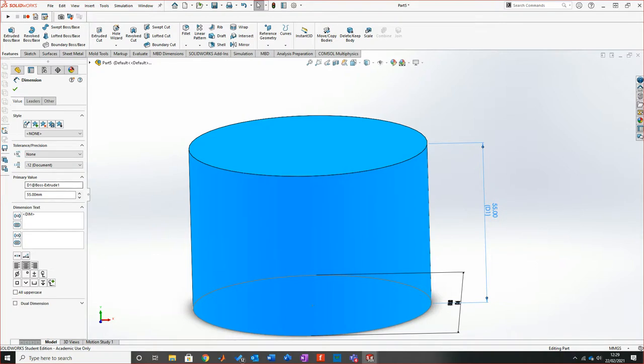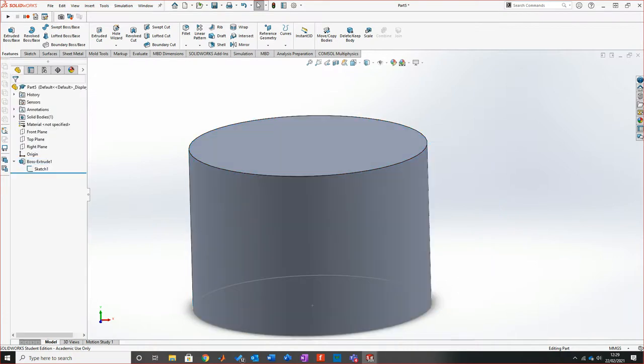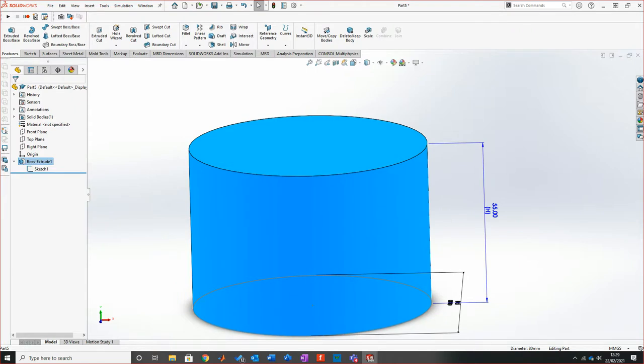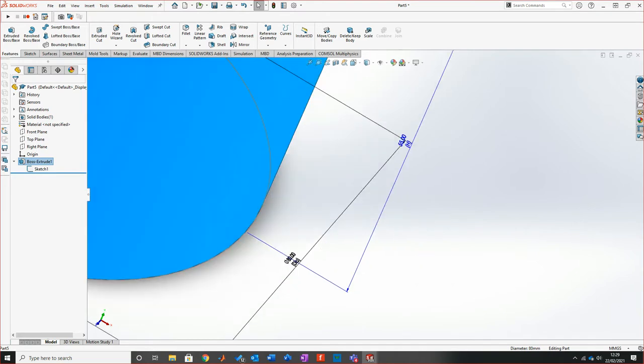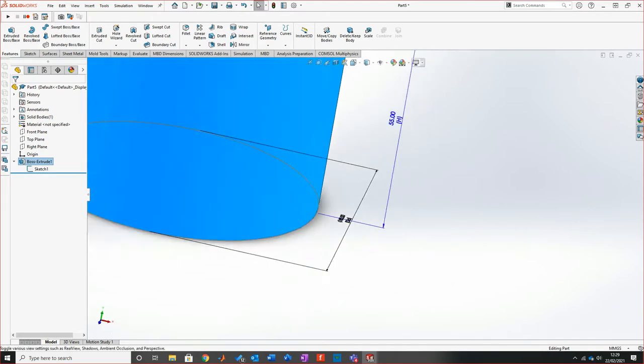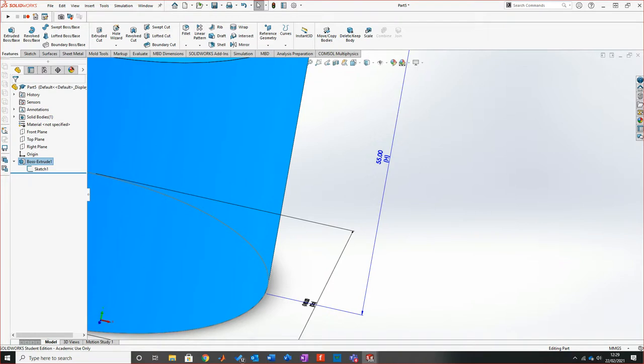on the left here, I've got D1 at boss, so I'll just call this H for height or whatever really. So if I click back on, whoops, click back on, see there I'm on D, see there my dia sits there, and there they are. There are my named dimensions. Now if I record myself changing those dimensions, it will record the name, and it will also record the value.